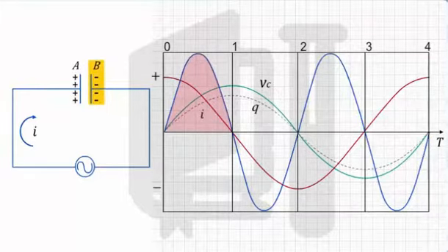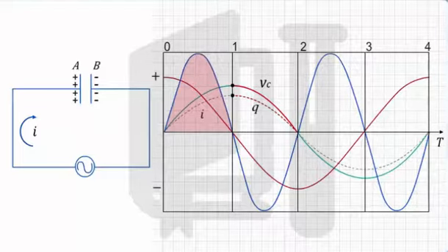The plates are fully charged at the instant 1. The voltage across the plates is in phase with the charge Q, and peaks at time t equal to 1. As the current and voltage are both positive, it means that the power is positive. Positive power refers to charging of the capacitor. Hence, power is being absorbed by the capacitor and it gets charged.